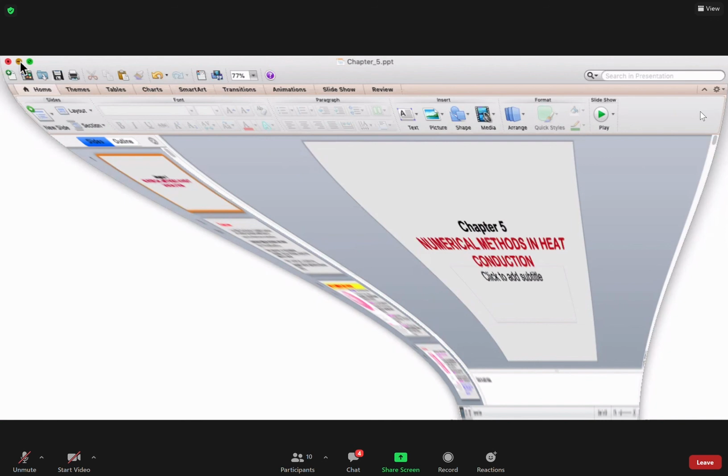Okay, look at here. The case we had, this part, right? This one here. We mentioned if the case is like this, this was the equation that we had. This is the general solution, no restriction. We mentioned if it's more than 0.2, we use the simplified equation that you have here. This is for the case if the Fourier number is more than 0.2, okay? But if the case is not, you can use this graph.